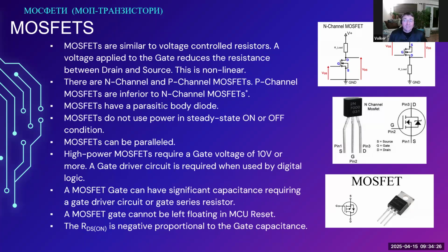And ideally, you should be doing that with external diodes for MOSFET bridges too. But these cheap Chinese motor controllers usually just say, okay, the body diode is good enough for this purpose, and they do not put any additional diodes into the circuit.